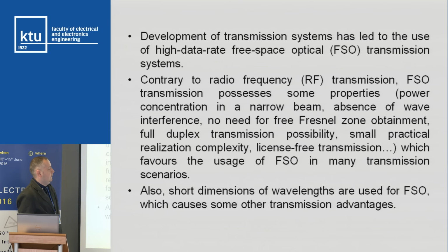First of all, when this signal transmits through the atmosphere, some wet parts of air or fog or something like that could cause the refraction index of the atmosphere to change, and the signal would have some sort of scattering, and that would cause the irradiance to change in space and in time, and irradiance could be observed as a random process.